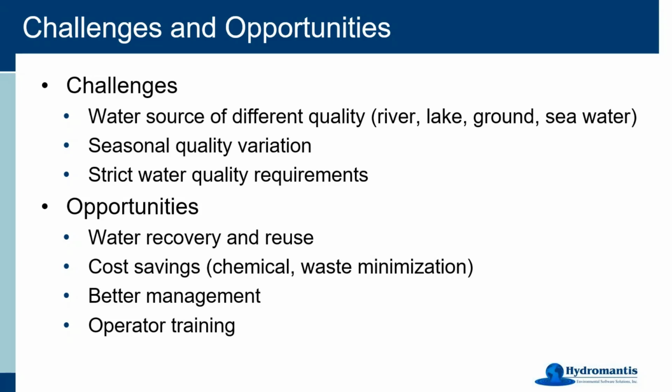The other part is, of course, directly related to cost savings. As I said, water treatment plants are more chemical intensive, so the more chemicals we add, the better treatment we can get, but it also leads to other problems. For example, a lot of solid generation might happen if you overfeed your chemicals.